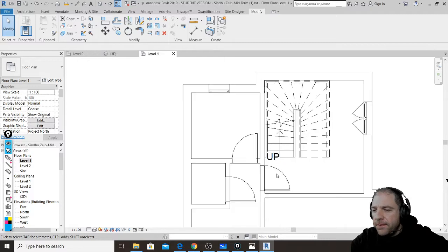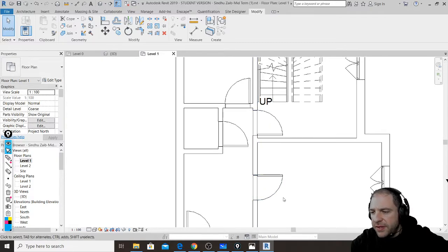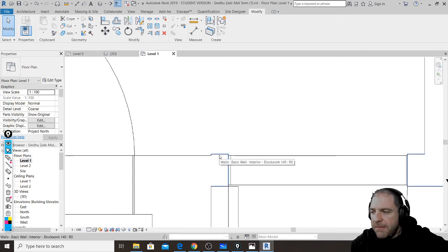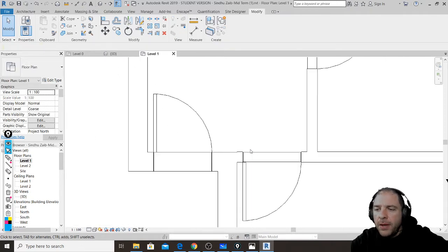See this. First question is, have you used the method that is you have translated PDF into AutoCAD, then scaled the PDF, then scaled the AutoCAD, then imported AutoCAD inside Revit or not?